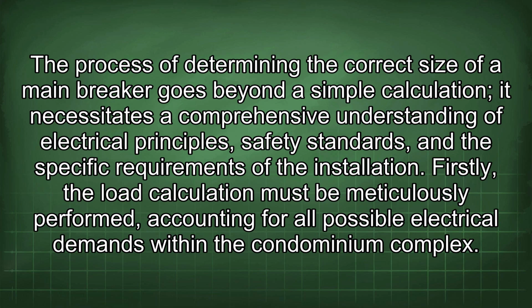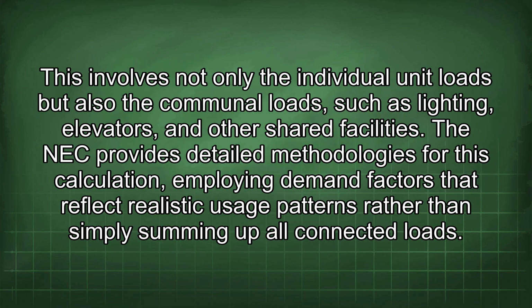It necessitates a comprehensive understanding of electrical principles, safety standards, and the specific requirements of the installation. Firstly, the load calculation must be meticulously performed, accounting for all possible electrical demands within the condominium complex. This involves not only the individual unit loads but also the communal loads such as lighting, elevators, and other shared facilities. The NEC provides detailed methodologies for this calculation, employing demand factors that reflect realistic usage patterns rather than simply summing up all connected loads.